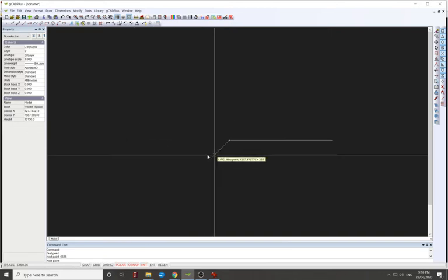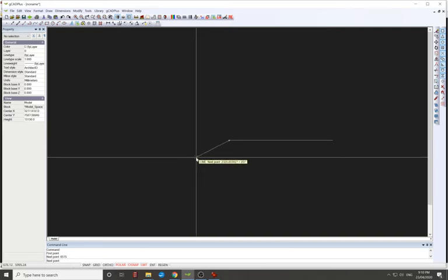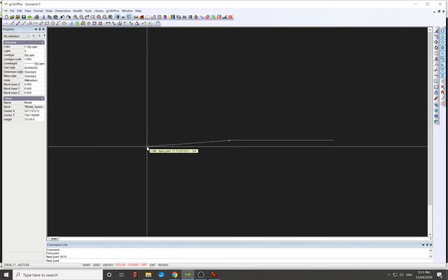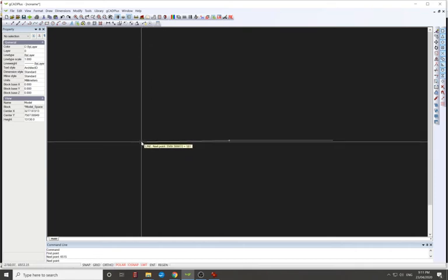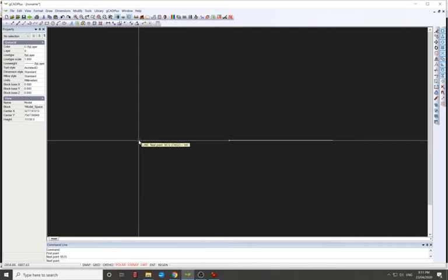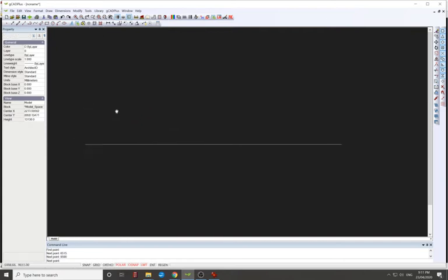Because the tape measure I have is only 10 meters long, when I'm measuring the wall, I might stop at a certain point which I can keep my eye on. In this case, I started on the other back corner and I measured to 9,590, and I marked that. And then from there, I measured the 6,515. I'm starting at 6,515 because my tape's only 10 meters long. I've got to go within 10 meters, and I think the sideway is only 15. So from there, we go 9590. Enter that, and that's the side.